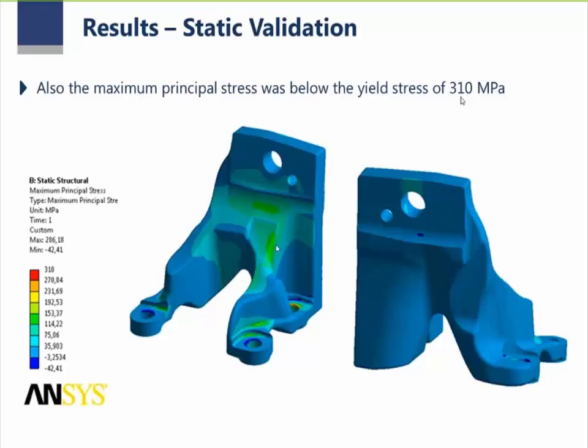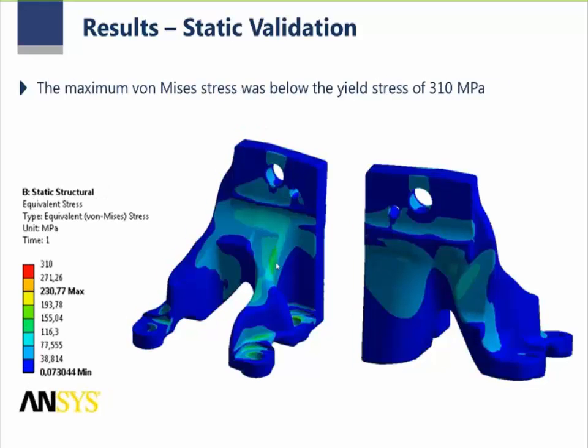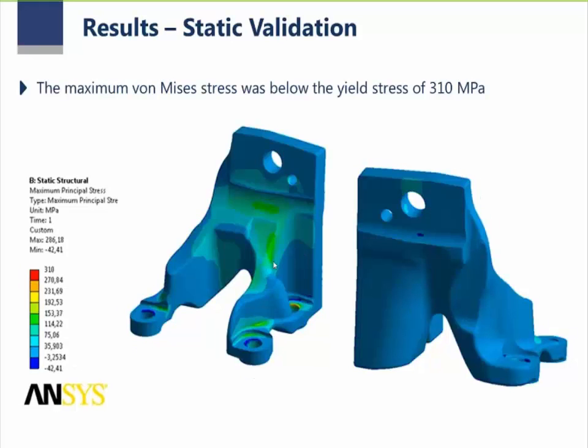And here you see some region of high stress. From the principal stress, you see this is in green here around 150, which is positive, which means a traction force for this region. And in the end, you see that this is, for example, the critical region for fatigue.